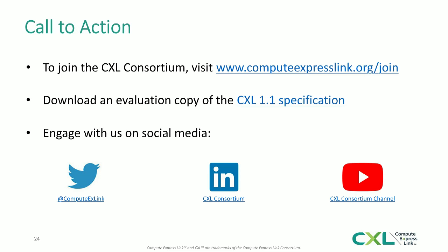Is ECC required to be transported over CXL.mem? So I think it depends on what ECC is meant in this context. But if we're talking about media-specific ECC here, no, it does not get transferred. I mean, cache lines themselves don't. It's just a data cache line. You're not sending ECC with it.